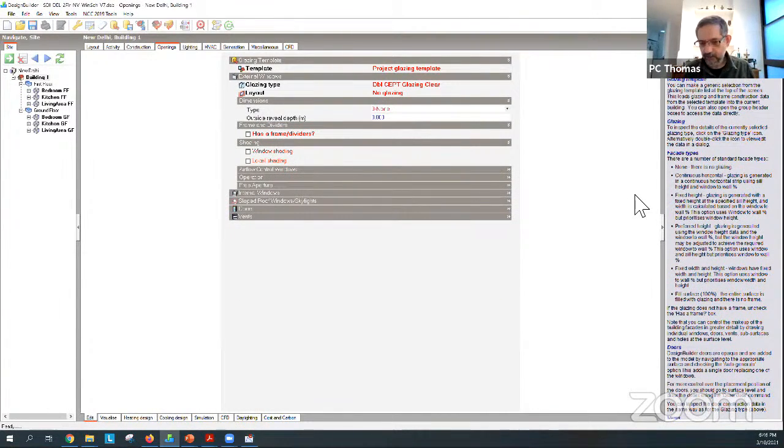When you draw a component block that's representing a tree, and you want to make sure that in winter the leaves fall off, then you can change the transmittance schedule of the component block, and that way you can adjust how much solar radiation is passing through the tree and reaching your window in the winter. So many options there. Let me just check here. Yes, I think I've covered pretty much of what I wanted to do. I think we can probably stop.